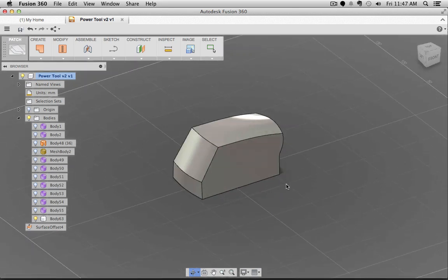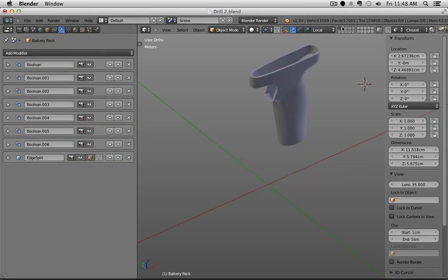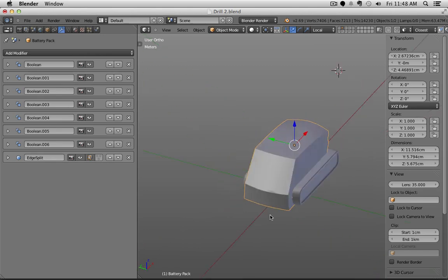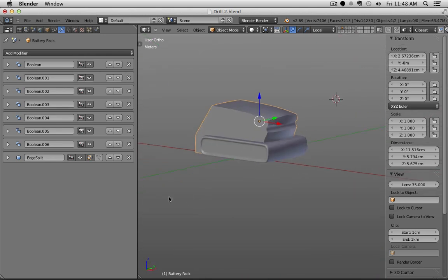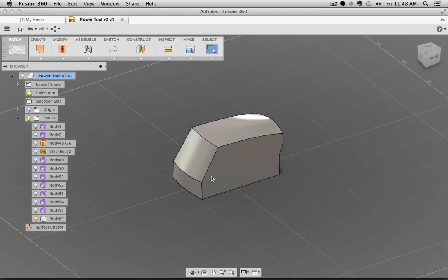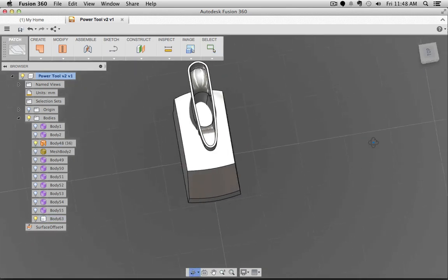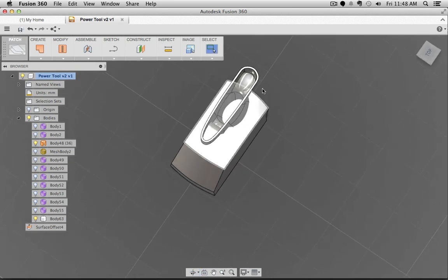So similar process. With NURB surfaces, it works a little bit different, but I end up actually with exactly the same design or model I developed inside Fusion. And that's a really great part. And then, for example, the next step, I would have to finish this one, round the edges, and then maybe try to see how I can join those parts.